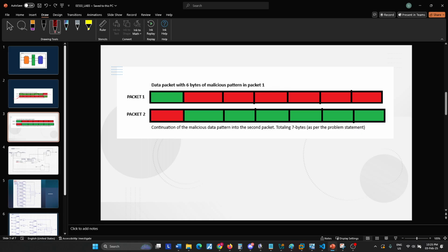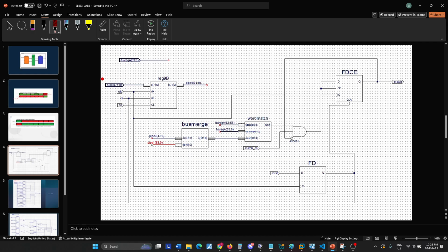The input stream is an 8-byte packet plus a 1-byte pattern for a control signal, which tells the FIFO some information about the packet. This totals 9 bytes as we saw in the system, where 8 bytes are the actual data and 1 byte is the control signals.